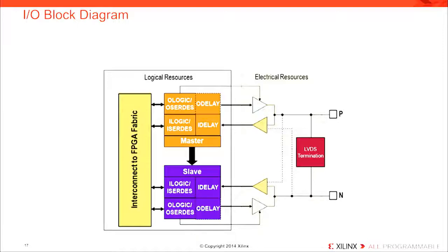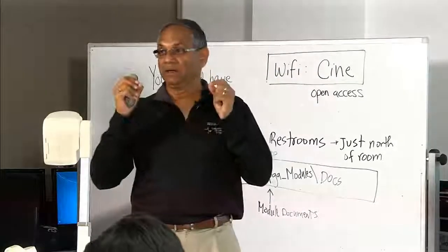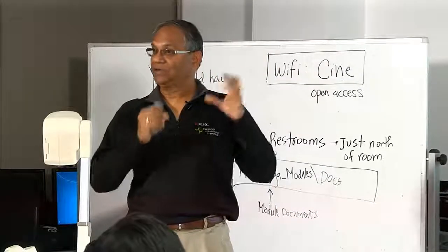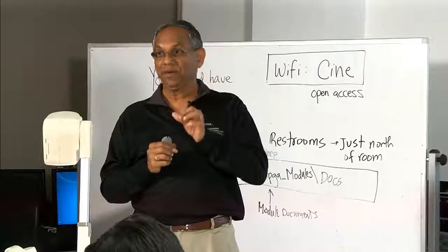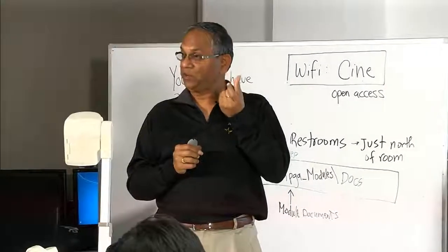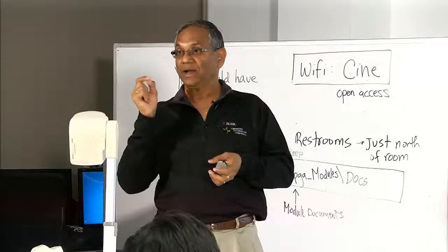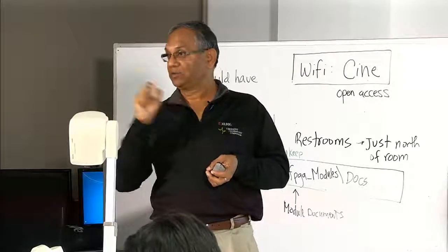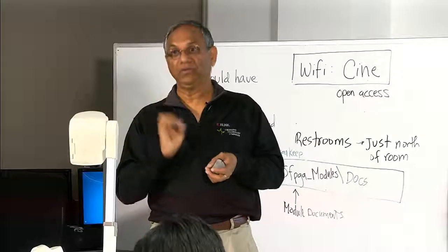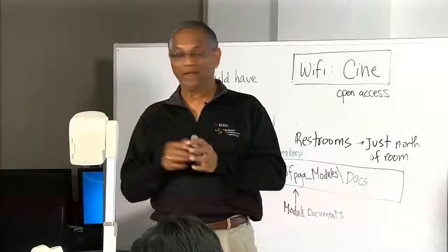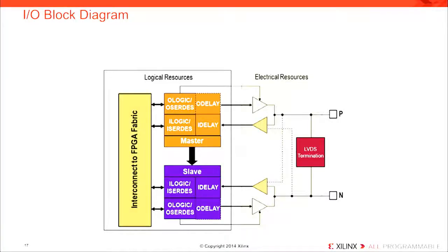So if you are using differential input or output, the positive should connect to P and negative should connect to N. If you look at the I/O chart of the chip, for each and every pin, the pin mnemonics will have _P and _N. So you should assign the right pin to the right voltages if you are using differential. If you are using single ended, you can use either one or both of them.